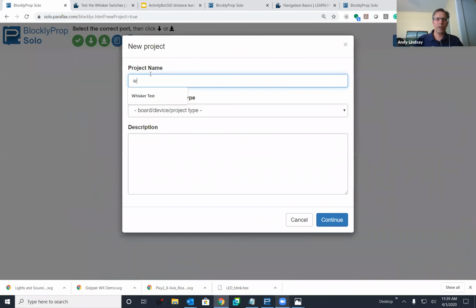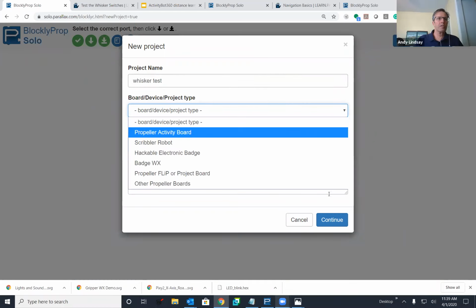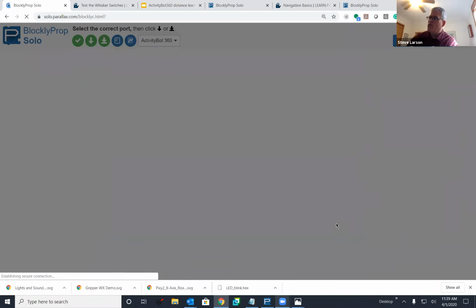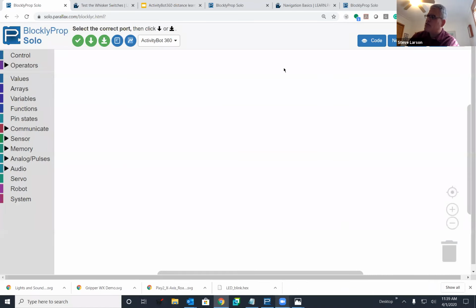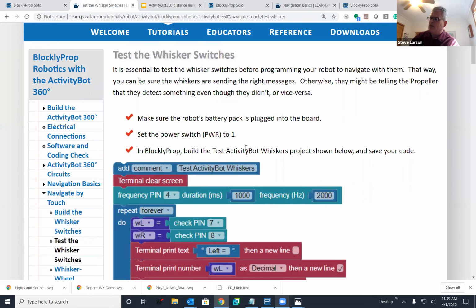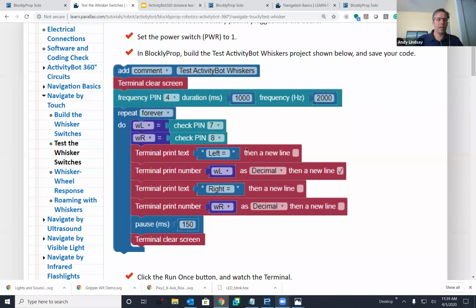Did that program combine distance and speed blocks by chance? Yeah. Well, I have robot set acceleration for distance to 50 ticks, which is the sluggish. Okay. And then I have robot set speed for distance at 128, so I went to the full speed. Okay, yeah, and so there should be a set acceleration level for speeds as well.